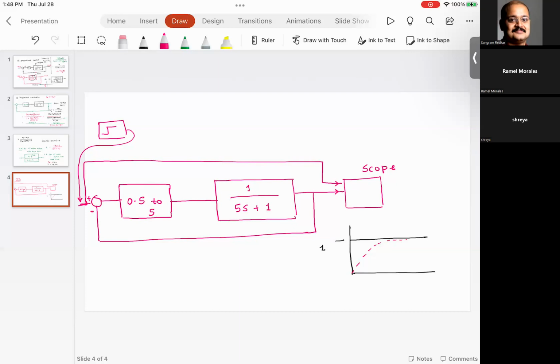Summing junction. It's constant. Yeah, right now it could be constant. Connect basically just like that. But this is a mathematical element, you have to add it as a gain. It's not constant. Gain will have an input and an output. Constant is just the gain. That's the gain block. Yeah, that's the gain block. You got it correct. A number of you got it correct. You want to make connections, from here to there, from there to there. What you want to do is have a scope block.